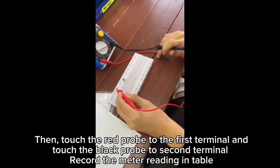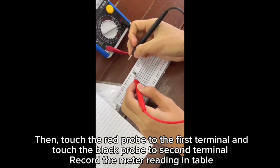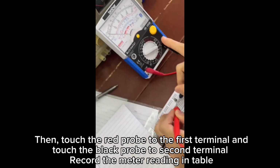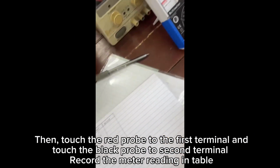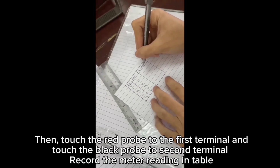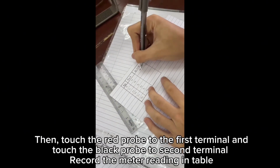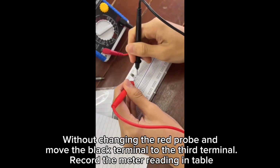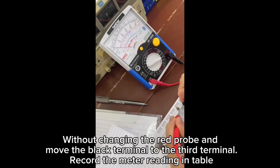Then, touch the red probe to the first terminal and touch the black probe to the second terminal and record the meter reading in the table. Without changing the red probe, move the black probe to the third terminal.